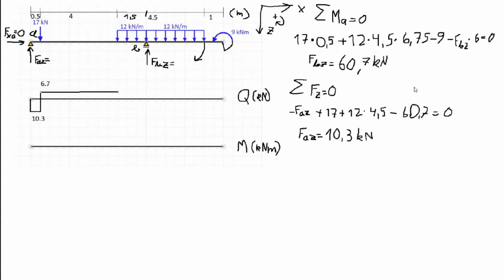And distributed loads will create a linearly growing or decreasing shear force diagram, because the way you can think about it is you have a very small, let's say 1.2 kilonewton worth of concentrated load after each 0.5 meters, or however little amount of distance after however little amount of distance. This will create a small stair stepping where you have 1.2 plus 1.2 plus 1.2, but we will just draw it as a linear line.